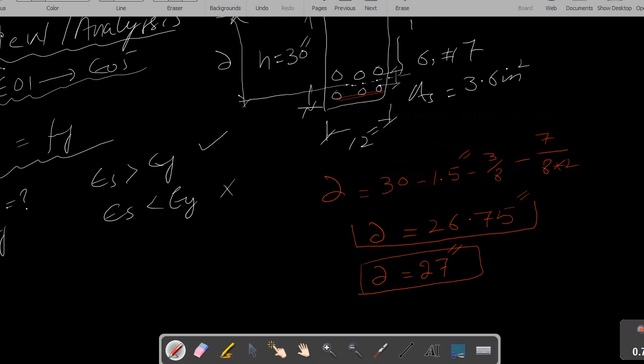From the previous discussion, we see that when D decreases, the area of steel increases, and if you increase the effective depth D, the area of steel decreases. This is a direct relation between area of steel and effective depth. So as our depth is decreased here, although the difference is very small, it will affect the area of steel a little bit.